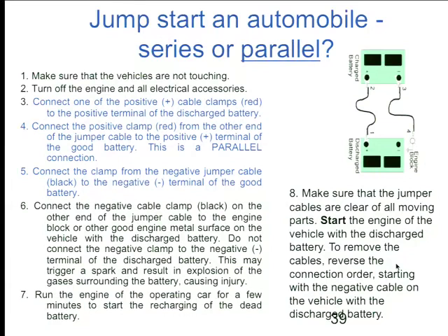What do you think? Do I put plus to plus, minus to minus, or minus to plus, or plus to minus? Let me say plus to minus? Plus to plus. I like that, yes, because you're just trying to make this guy do what this guy was doing. So you put him in this way, plus this way. So what you'll have is a cable that is red with a clamp on it, and you clamp it here, and the red cable goes to the same type of polarity, and the black one goes to the same type of polarity.